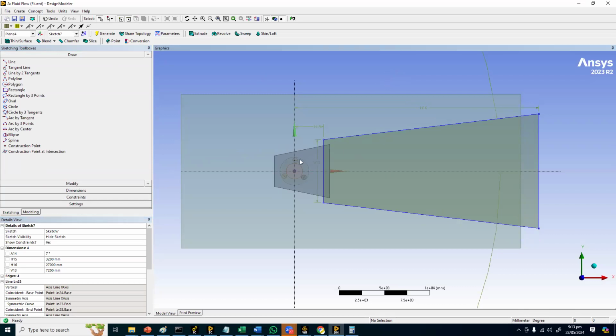If people also want the mesh to be refined in the whole wake region inside the domain, this is also possible. But let's make it smaller. Otherwise this will take a lot of space, and it will refine the mesh, and this will actually take more time to run the case with more mesh cells. So that's why I'll limit it to maybe 15,000. That's okay. Or maybe 13,000.